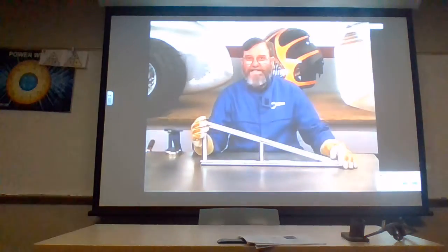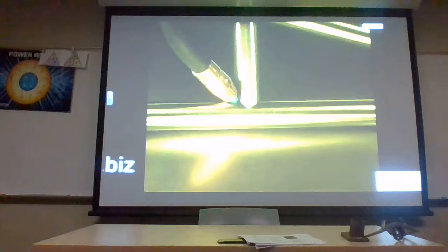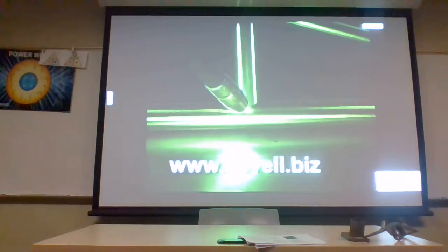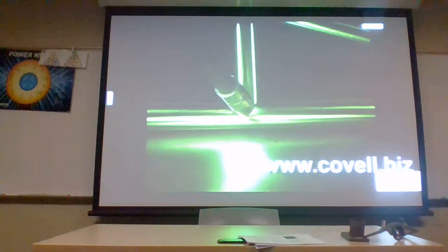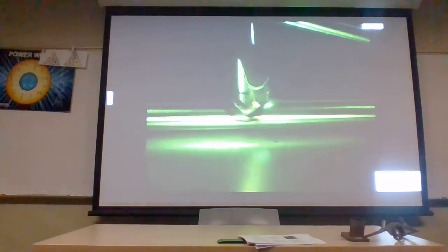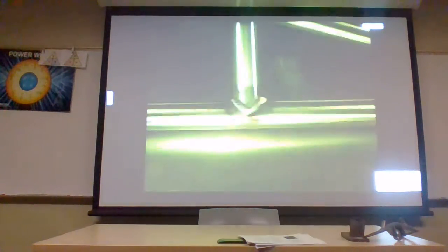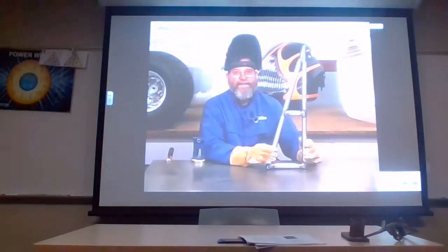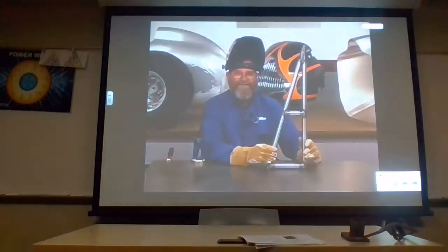Some of the most challenging joints to weld are at the intersections of round tubing. A joint like this can be viewed as a fillet weld in one area, which makes the transition to a lap joint in another. Also, you want to keep the gun angle equal between the faces of the tubing as you're welding, while keeping the travel angle around 10 degrees. It takes a lot of practice to keep your motions coordinated when navigating a complex joint like this, but the more you do it, the easier it gets.